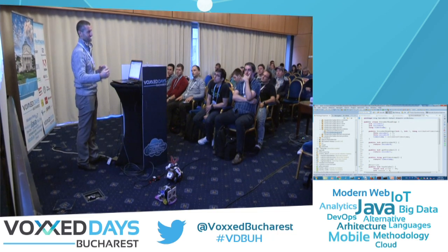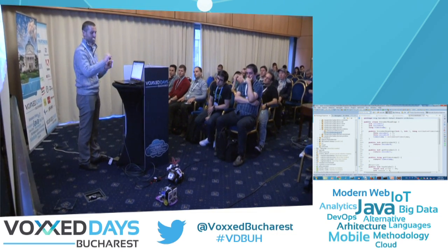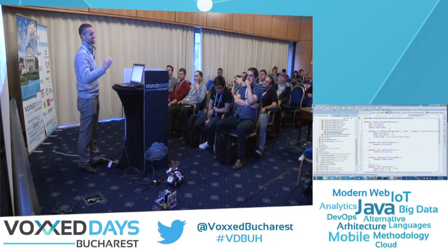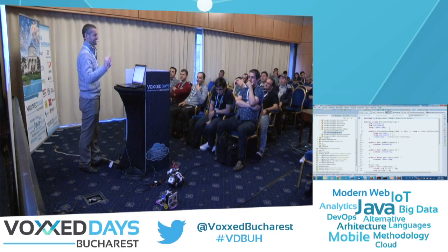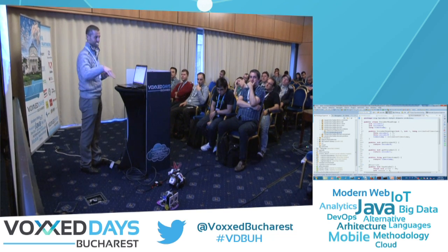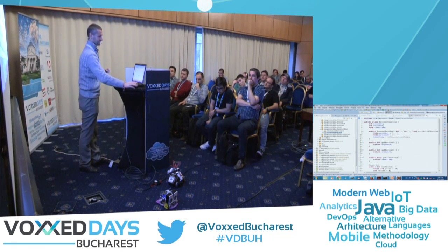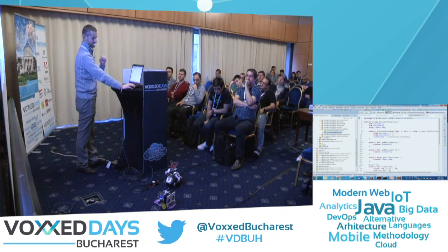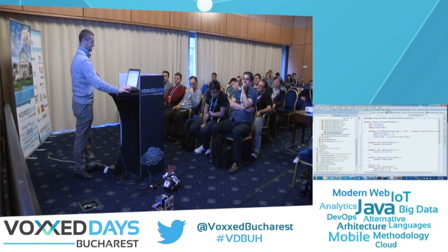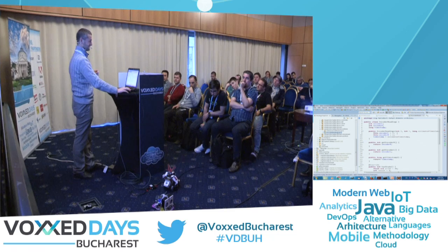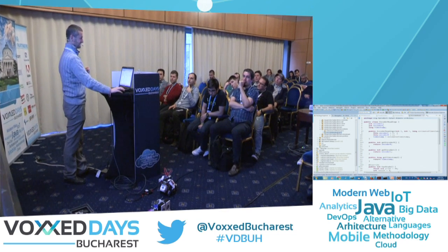And it has a hardware USB, which means that if you mess something up, you don't have to upload your bootloader in an exotic way, because it's hardware-based USB to serial conversion. It's implemented in the microcontroller of Arduino Leonardo, which is different from the Arduino Uno series of microcontroller, and the Mega, all of them, of course.